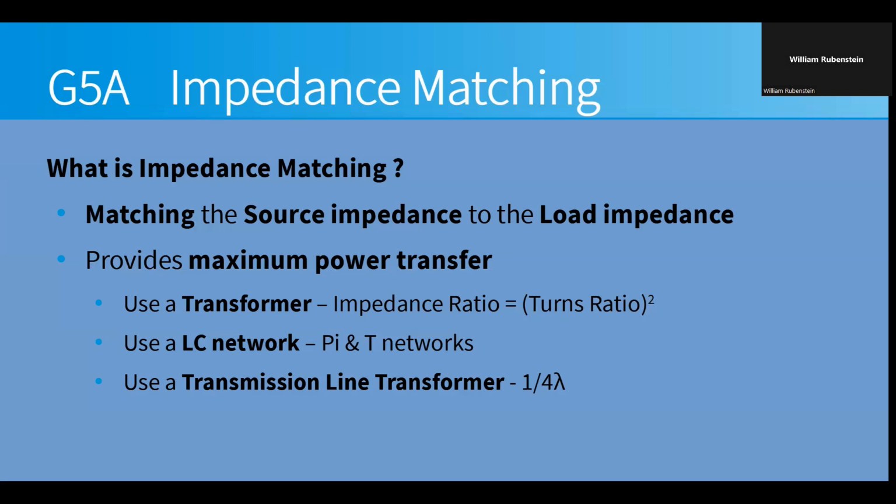Yeah, and even though they call these antenna tuners, they don't tune the antenna. It's a matching network. To tune the antenna, you have to actually physically go change the length or add a capacitive hat or something to the antenna. This is at the transmitter end where you're feeding.